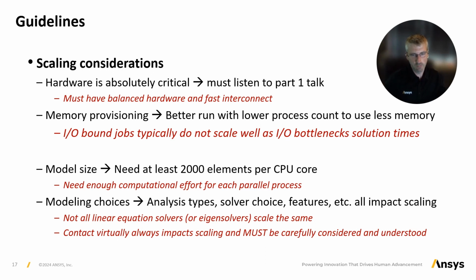In addition to that, it's also important that you consider some of your modeling choices. And this is a bit of a sticking point because there are a lot of different analysis types and equation solvers and other finite element features within the Mechanical APDL product. And these different features will all have some impact on the scaling of your simulation. So it's important to think about what sort of linear equation solver or what eigensolver you are using and how those solvers scale. But also, what are some of the boundary conditions, like contact or constraint equations? These things need to be considered as they will impact the scaling of your finite element simulation within the Mechanical APDL product.